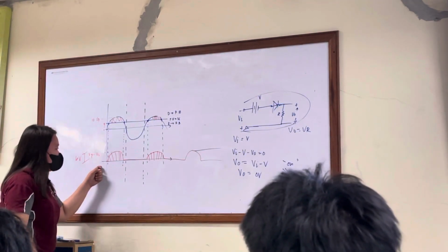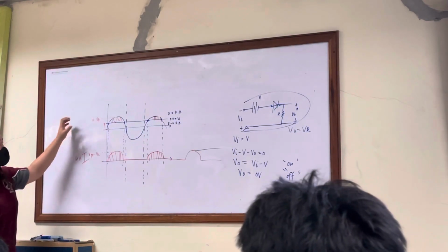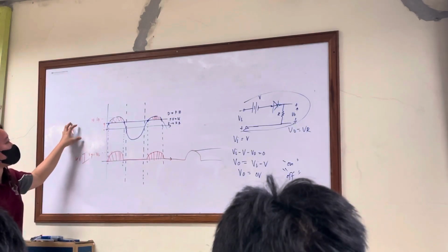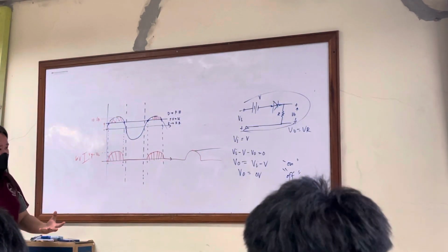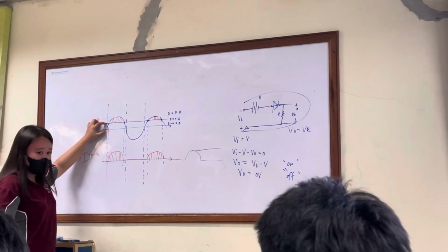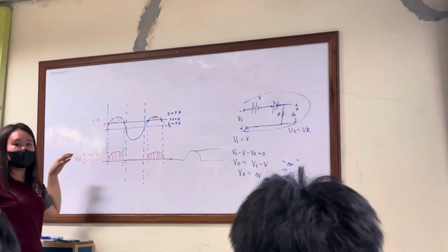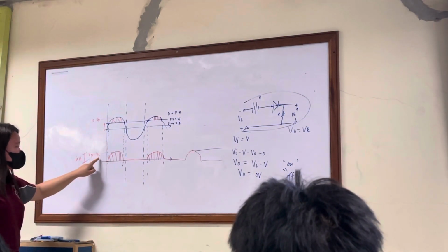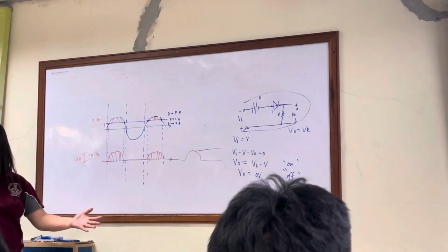Okay, this time you base it on what you clip off. V peak: you remove a portion from it. What portion is that? Your transition value. So the new amplitude of our output on the positive half is V peak minus our transition. Understood, everybody?